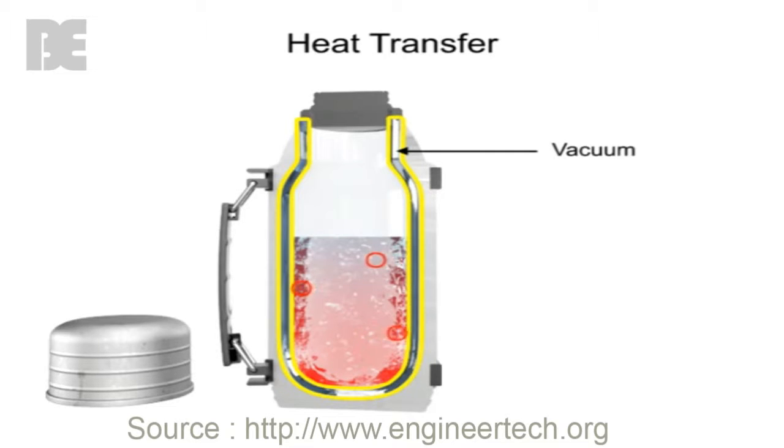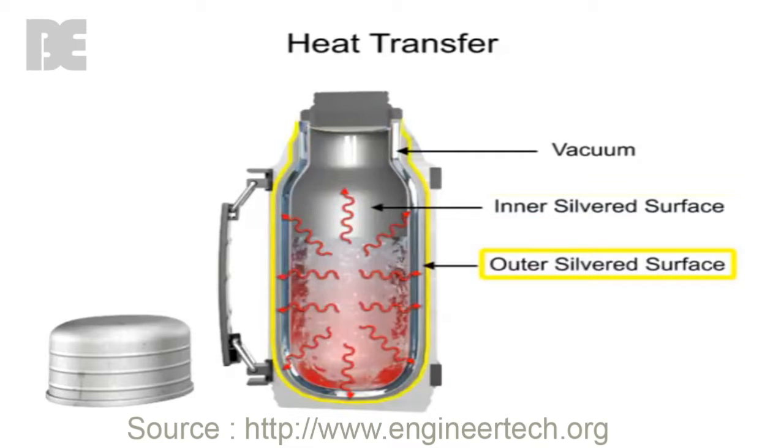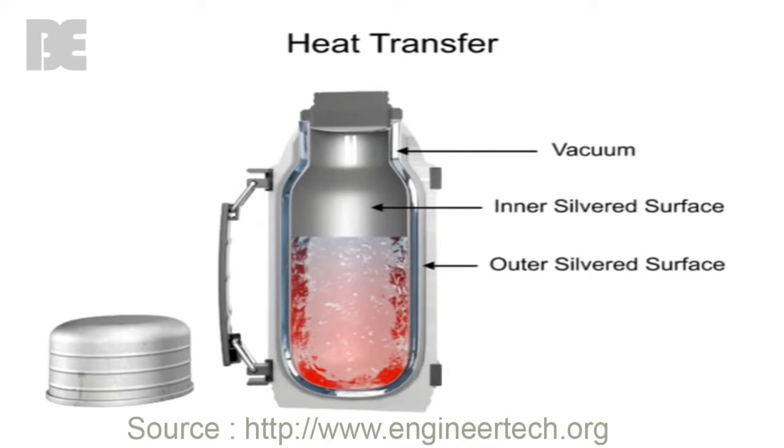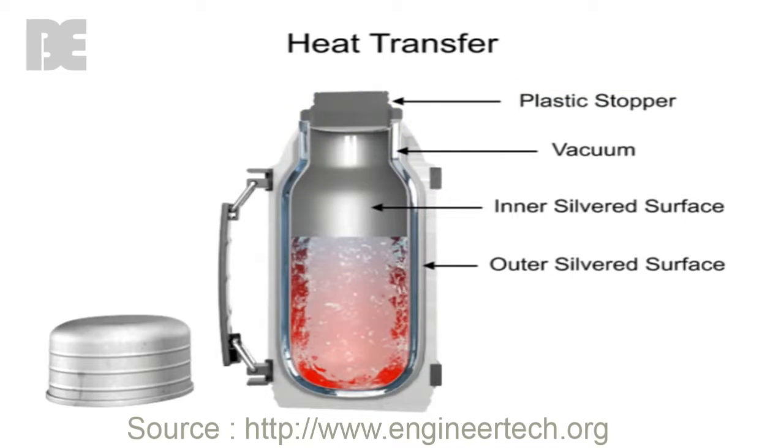The lack of physical contact between the inside and outside walls of the thermos due to this airless space also greatly inhibits the movement of heat by conduction. Heat loss by radiation is prevented by the silvered walls reflecting radiant energy back into the thermos. Some conduction of heat through the stopper and glass can be expected, but this too is limited because they are made of materials with very low conductivity. Thus, the temperatures of both hot and cold liquids can be maintained by a properly designed thermos that limits the transfer of energy through radiation, convection, and conduction.